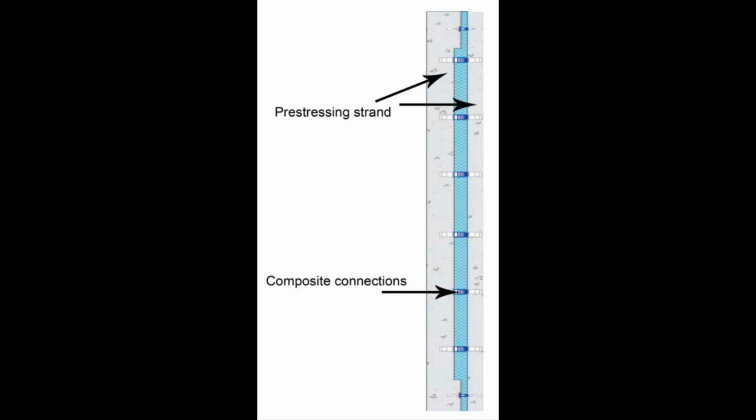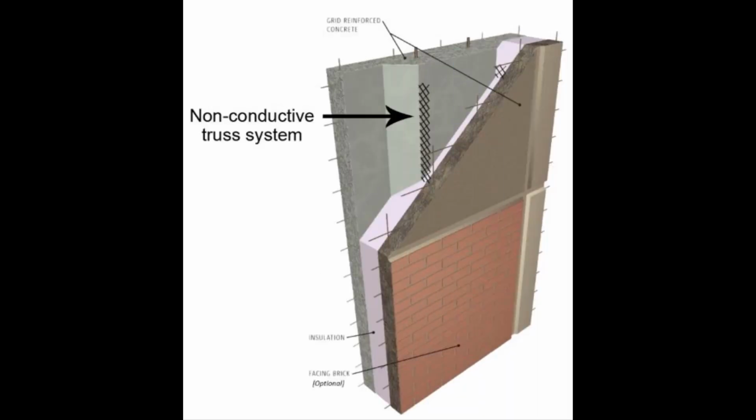Sometimes the panel is made solid below the floor line and above the parapet, outside the building envelope, to help with composite action. Unlike non-composite panels, composite panels often bow outward when exposed to direct sunlight due to the temperature increase and subsequent expansion of the outer withe. The characteristic is normal but should be taken into account if panels are attached to or abut against an intermediate floor mid-height. Then we have partially composite.